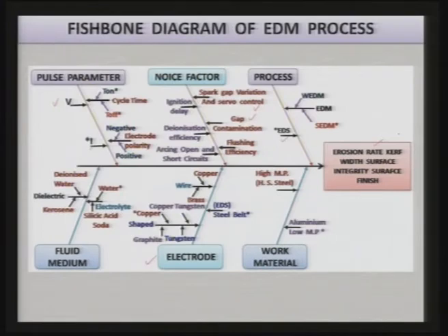This is a very important point, because EDM and wire EDM are thermal processes, that is, they are heat-dependent processes where material is melted and vaporized due to the heat generated at the point of sparking. Since the temperature is very high in the localized area, it normally leads to what are known as micro cracks, and micro cracks in the machine component are detrimental to the performance of that particular component.